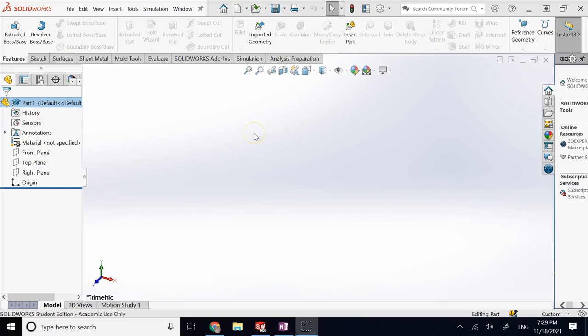So let's go with a simple example. Let's say you want to make a simple chair. You have the back part, the sitting area, and the four legs, right? So you have 6 objects in real life. You make those 6 objects and then you nail them together, or if they are made of metal, you weld them together. For these areas where you have a solid, permanent, or static connection, multi-body is really useful.